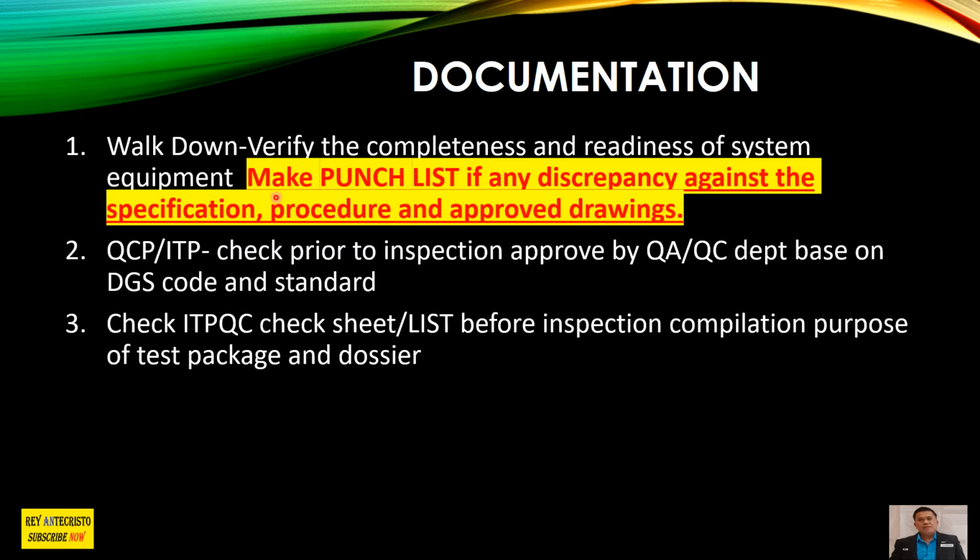And now the construction team, which is the project management team from the office, will bring these documents, what we call the mechanical completion dossiers. The dossiers will be brought to you, and whoever is responsible signs the MC dossiers. You can sign as an engineer, or the team leader, or some QC department, depending on the organization. But the most important thing is that all of this is captured in the mechanical completion dossiers.